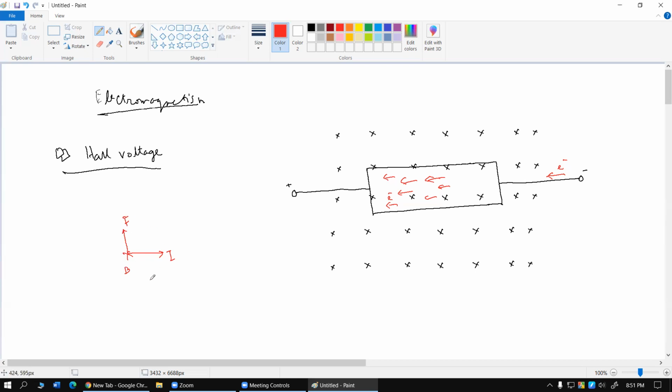If you extend out your left hand, your index finger is aiming away from you, which is into the page or into the screen. That's the magnetic field. The middle finger is the current direction, the conventional current direction, and the thumb gives you the force. Now, this is applicable for conventional current. If we want to do the same thing for electrons, which are negatively charged particles, we just have to use the force in the opposite direction.